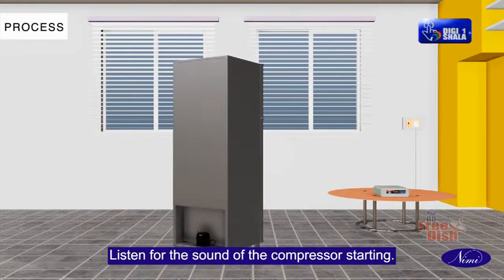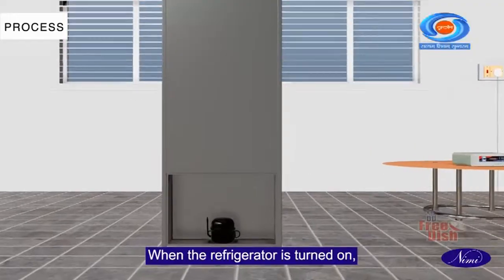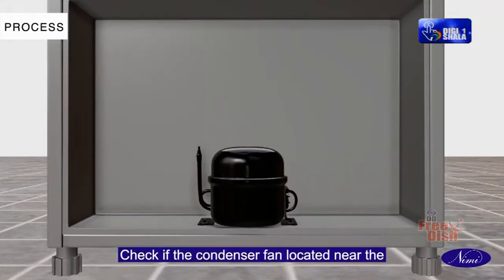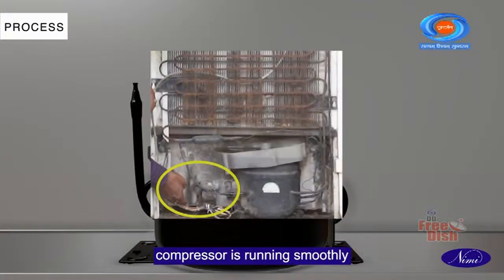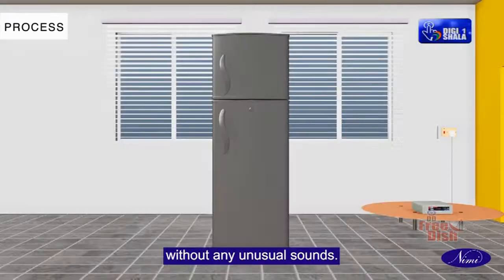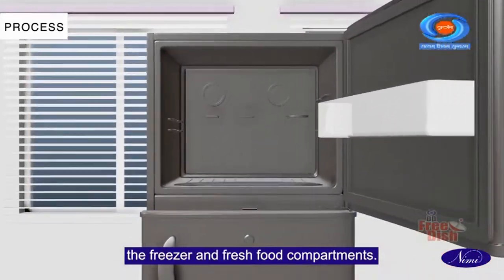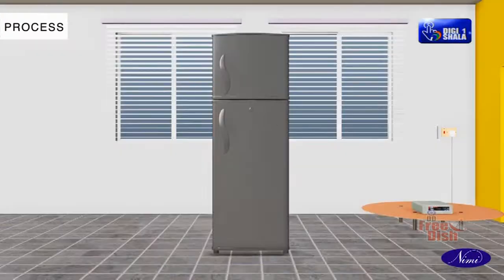Listen for the sound of the compressor starting when the refrigerator is turned on. It typically emits a low hum when running. Check if the condenser fan located near the compressor is running smoothly without any unusual sounds. Feel the air circulation in both the freezer and fresh food compartments. The air should be cool and consistent.